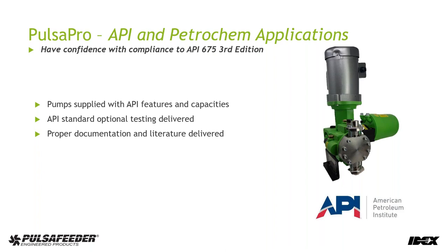Repeatability and linearity, mechanical run tests, sound level tests, positive material identification. We're equipped and ready to provide those services. We already do the standard hydro test and steady state accuracy tests that are required by API as a standard.